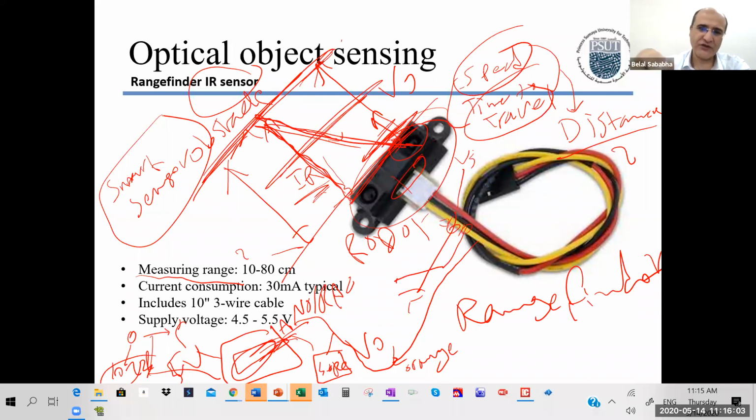There was a threshold, and the board had the IR transmitter and receiver, and a potentiometer to change this threshold. That kind of sensor, IRs, are digital, so you can take it to a digital port. If you read a 1, then there's something within a range. If you read a 0, then it's clear.